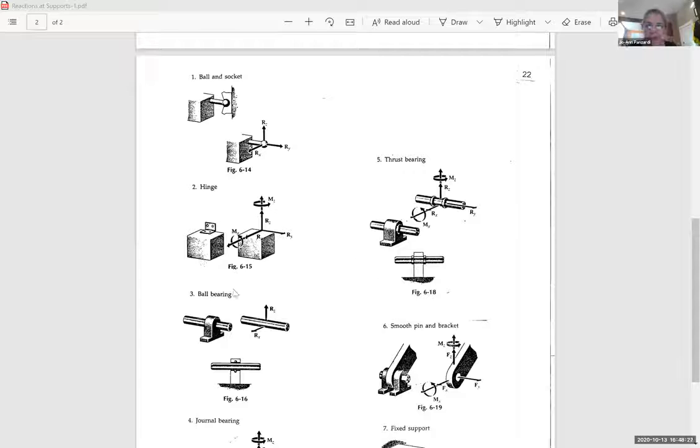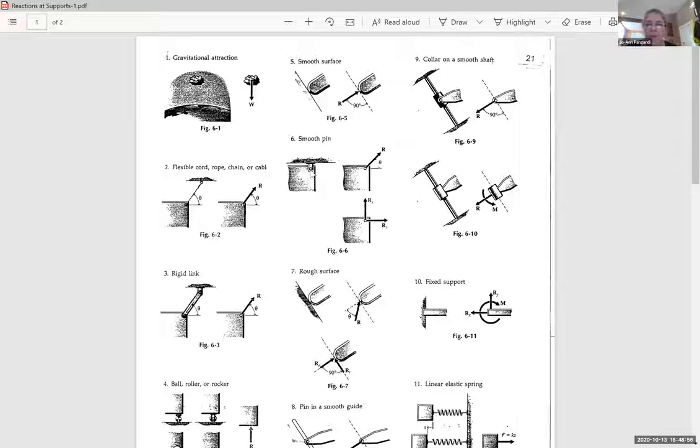So let me just explain that again. When we look at a hinge, we're trying to figure out how it could possibly break. Because as an engineer, we have to design it so it doesn't break. So we need to be able to calculate the values that it can resist, because it will never break by spinning in the Y. If you only rotate it in the Y, it won't break. So in the pin connection, I could spin a pinwheel as much as I want, and I will never break it if the only loading that it's experiencing is rotation. But if I start pulling on that sucker, I could break it because I could break the pin. So reactions at supports are the items that it can resist because we need to calculate what they are.